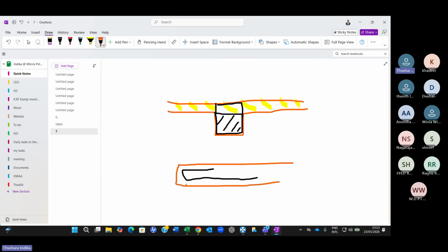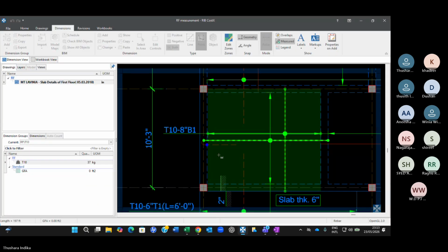And this is the bottom bar and it comes up and it goes a certain distance. So the vertical part, of course, you have to reduce the cover. Let's say this is a 200 millimeter slab, or 150 millimeter slab, and then you have to deduct 25 and 25. That means 150 minus 25, 25, 50, so 100 millimeter is the vertical part here. So you have to add that 100 and then the length of this. You can add extra if you want.